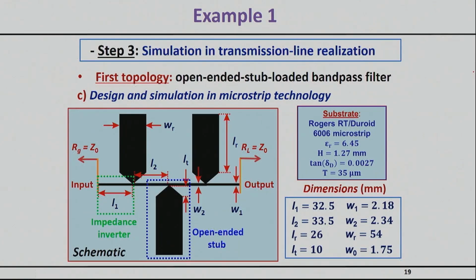So here's the layout that I will need. And hopefully this layout will bring a smile to your face because this is the width that I need for a 50 ohm impedance. And this is the width that I need for the 7.8 ohm impedance. So here you can see what I was explaining a minute ago. Yeah, we can push things, but there is a point beyond which things simply become ridiculous.